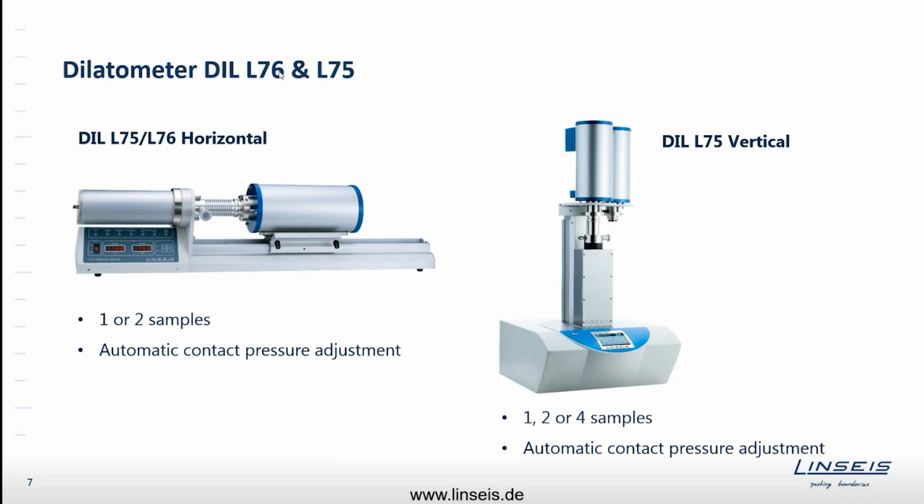So the L75 and 76 series, our push rod dilatometers, can be horizontal or vertical setup. The horizontal setup can measure 1 or 2 samples simultaneously, automatically adjust the force between push rod and sample, and you can set the force up to 1 Newton. The same in the vertical setup, you can measure 1, 2, or 4 samples, and you can also automatically adjust the force between sample and push rod.